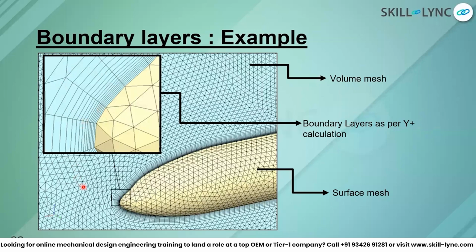If anyone gives me this picture and asks what type of simulation you're going to perform on this, the first thing I quickly understand is that these are boundary layer simulations. They are interested in what's happening near the wall or near the surface. That means the coefficient of friction, or maybe the drag coefficient. So you're trying to simulate the shear stress near the wall.